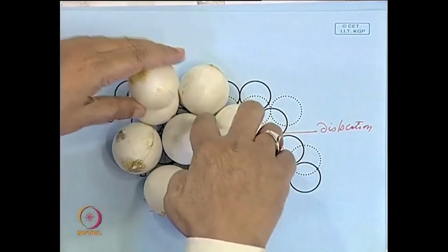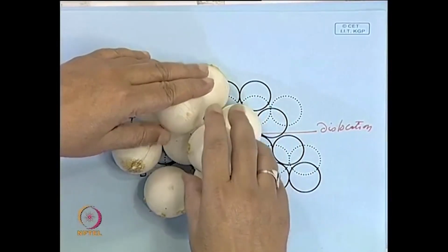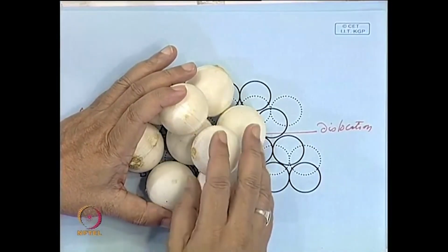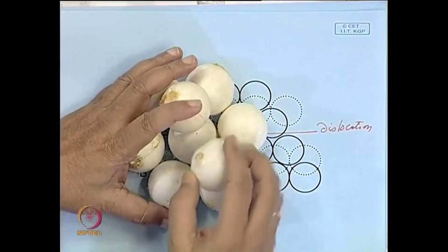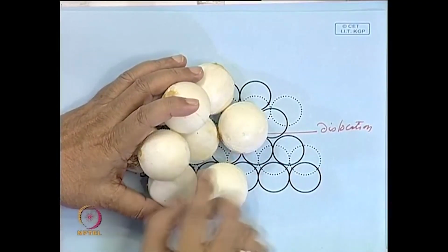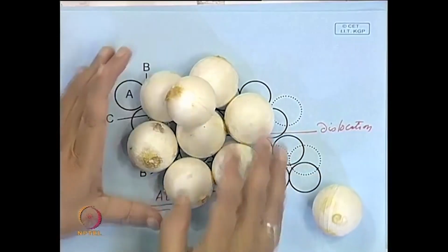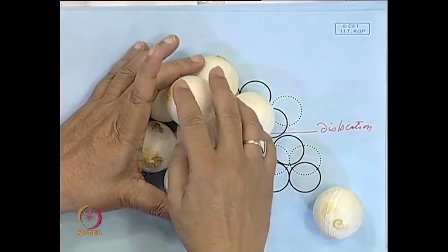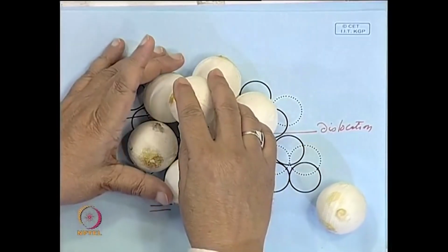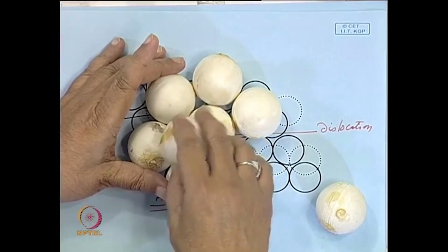So, this is one side, this is another side. So, here you cannot put, if you put it, it is coming here. So, part of this site is blocked. Similarly, here also you will not be able to put an atom. If you put, it will come here. So, that means let us say if this is a B site, now a perfect dislocation has to move from this position to this. This is the B site, this is the next B site.